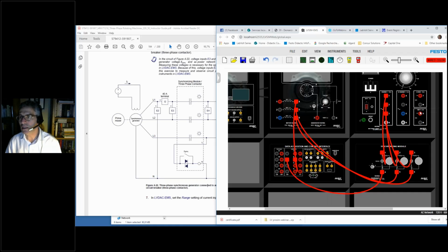So we will take the fixed 120 volt DC output from our power supply here to feed this electromagnet here, like this. We can use the fixed output because we have a rheostat here directly on our generator to be able to control the intensity of this field. Good. So these are the major electrical connections.